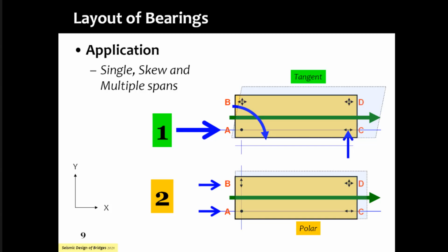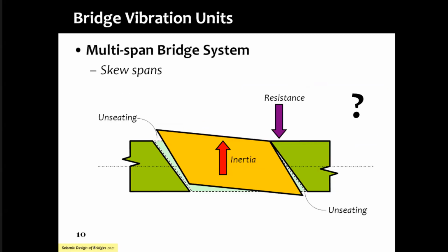So the key issue here is that you have to choose your bearings in such a way that you don't induce stresses during the normal functioning, that is when live load is passing on it, or under dead load self-weight action, or under temperature expansions and contractions. Same orientation of bearings will still be our friends for the seismic action.